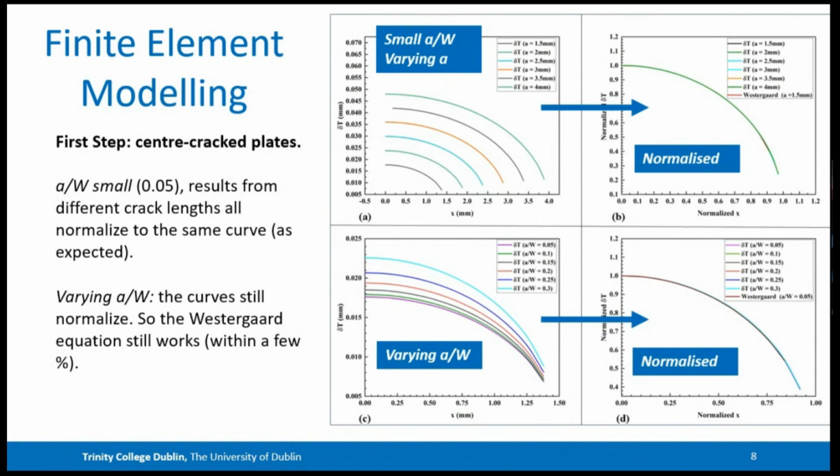And these are finite element results, so you see no difference. And they also are exactly predicted by the Westergaard equation. Okay, Westergaard was right, is what we've said so far. I haven't said much. So the next thing then is to look at narrower plates.